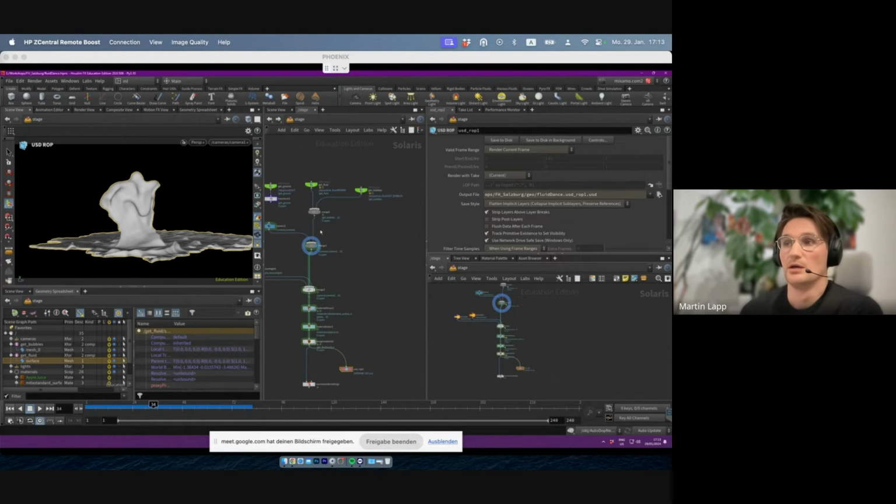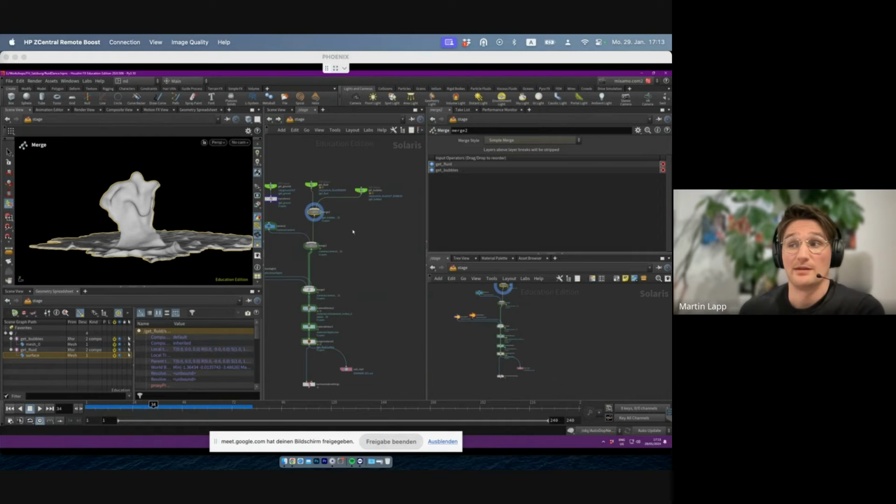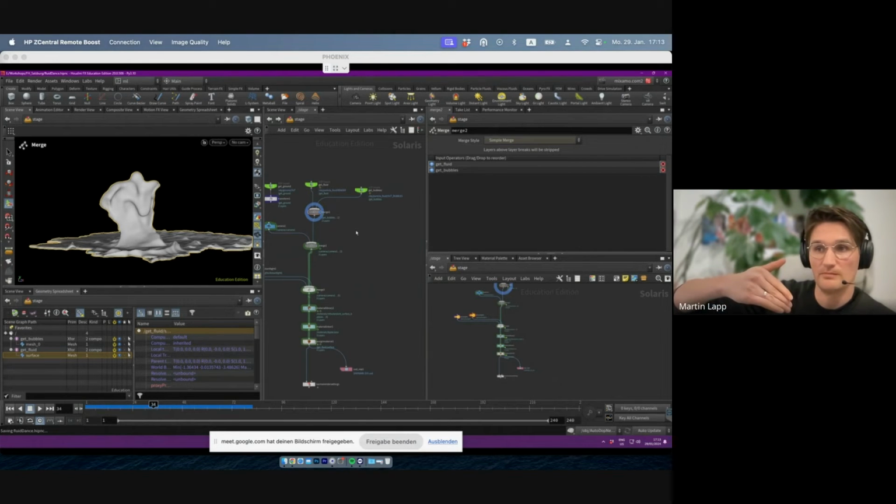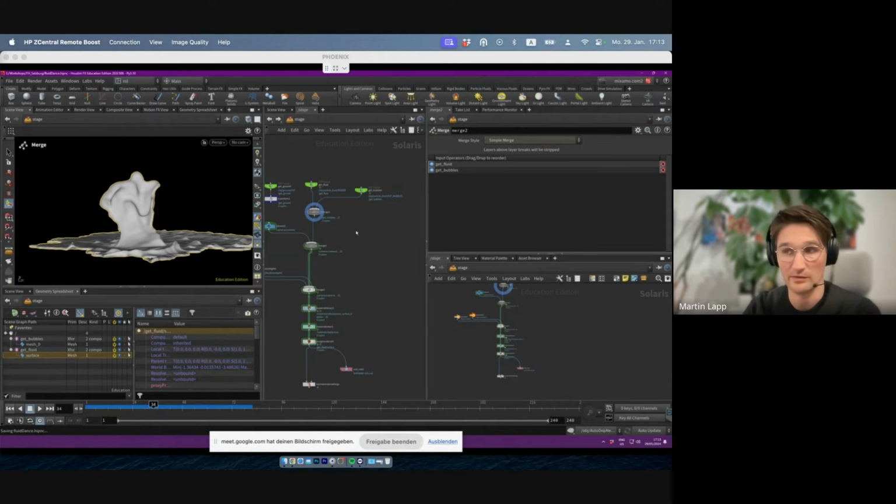So if assets creates an asset, it's saved as a USD. Then this USD gets handed over to layout, and layout is basically loading that USD in and adding its camera as a layer, basically, and saves this as a new USD. And then this USD arrives in animation, and animation does their animation. Animation layer exports that as another USD, and that's what we are opening at some point. We are adding our effects layer and passing that to lighting, and lighting is then rendering that resulting USD.